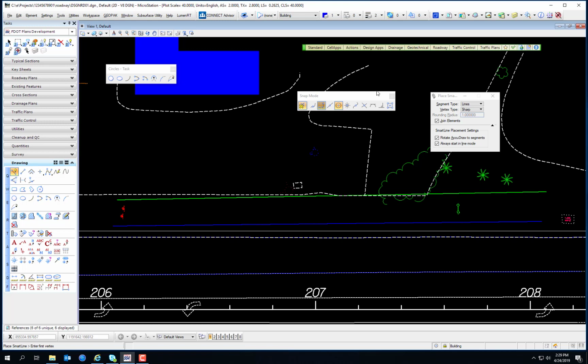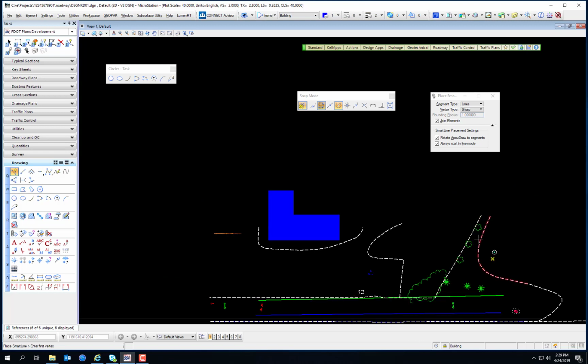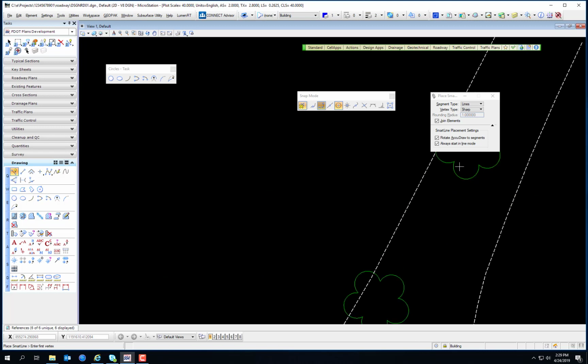It's different than midpoint because with a circle you can snap to the center of the circle. That's not a circle, that's not a closed shape here. But you see, that's almost a closed shape. That's an arc. So it's snapping to the center of the arc. It's the difference between center and midpoint. With the midpoint snap, it would be snapping right here. With the center snap, it snaps in the geometric center of that area.